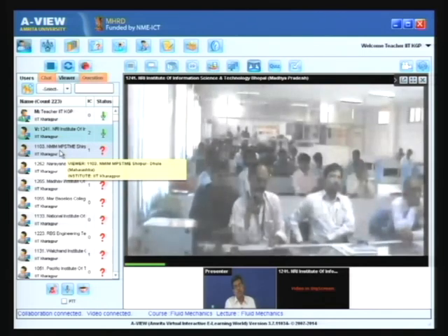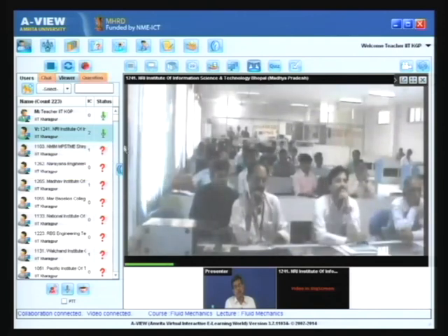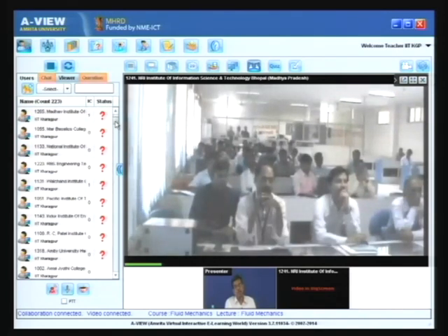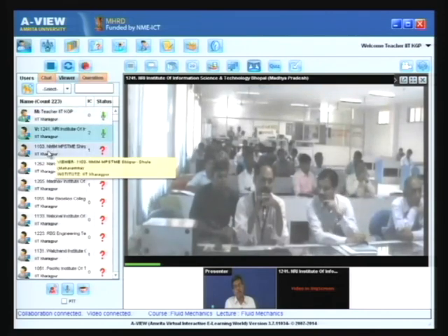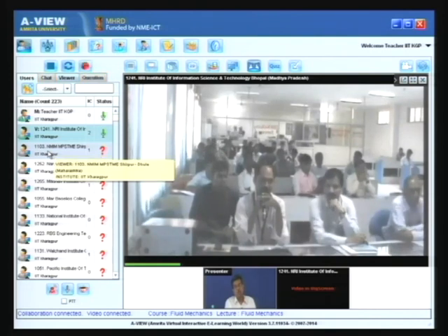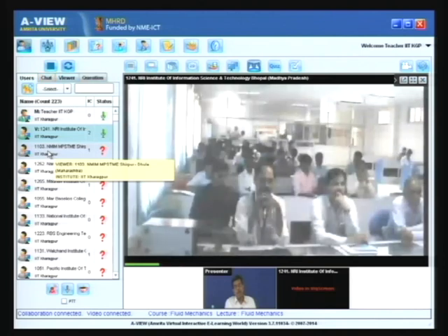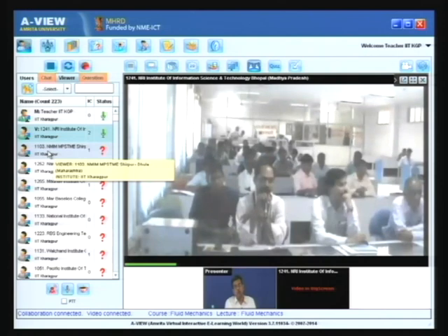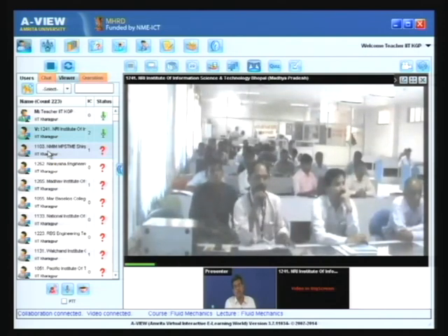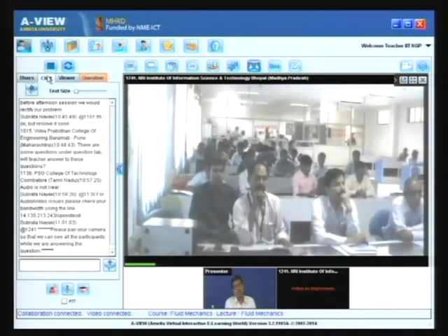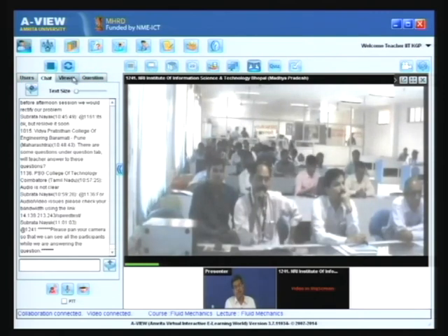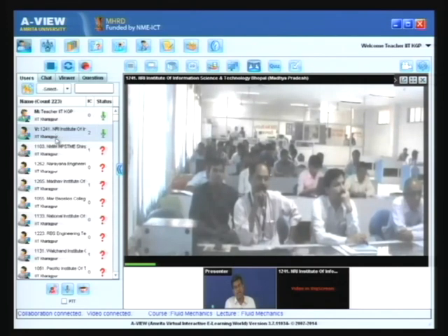That is nothing different. We take the turbo machine as the control volume, any impulse machine or reaction machine which is rotating and developing external torque, by virtue of which we get external power. Torque into angular velocity is the power. So you find out this torque or moment which we get from these turbo machines, or which is given to the turbo machines if it is a pump or a compressor, by similar application of the rate of change of angular momentum with the Reynolds transport theorem, as we did. It is as simple as that.